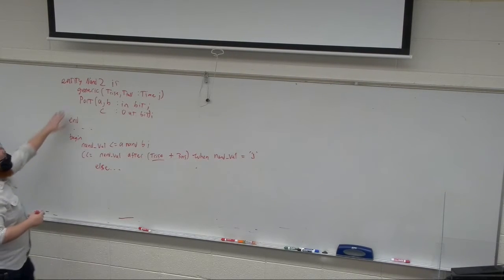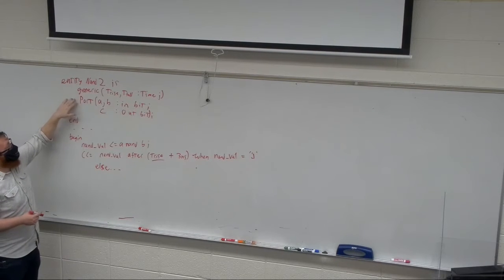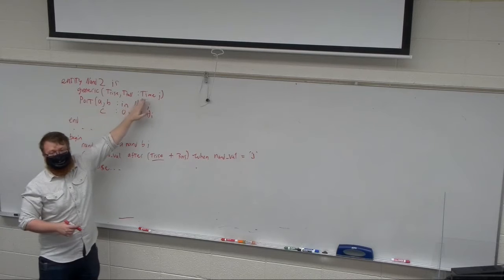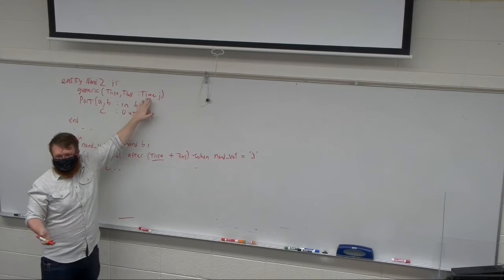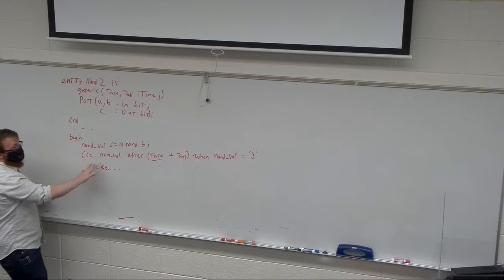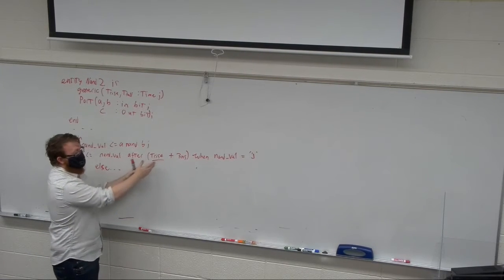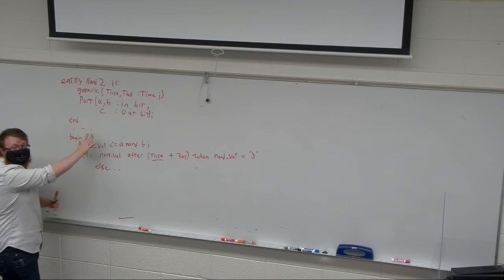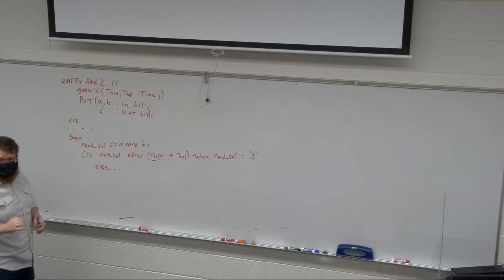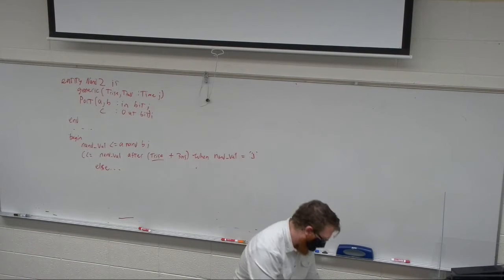So we create the generic statement. Just like port, right before it, we declare what generics we're interested in and what their types are. This type time, we know it's not going to synthesize. Then inside of here, I have this T-rise. That is not going to come from a declaration in here like a constant like we've learned in the past. It actually comes in when we create, in this case, the component.